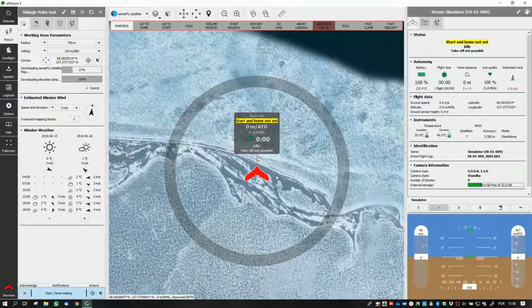So you have to be sure that you are cleaning all the landing area for some tens of meters. And when it is landing, it is good that the observer should be close to the landing site and should point you if you need to abort the landing or not. And then if he is landing, you can abort the landing just before he lands. Then you will fly up again, it will start hovering around your position, and you can shift a bit manually the landing position into a better place. But of course this will be visual, and that's why you need a bit more battery.